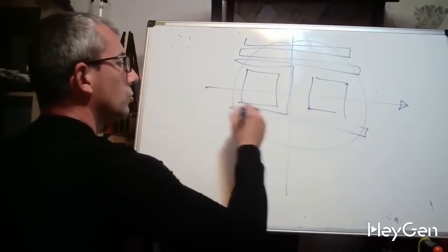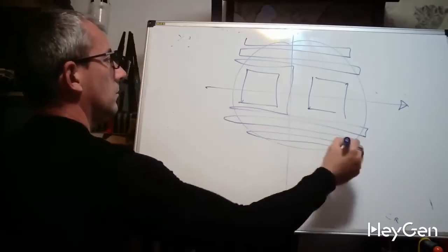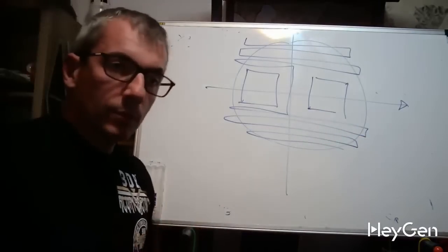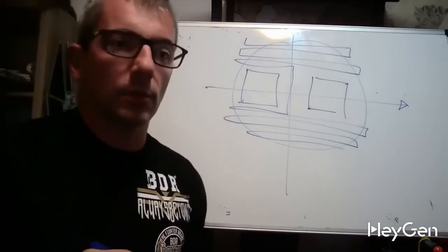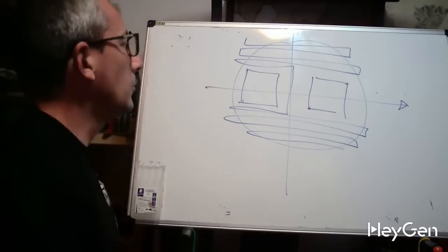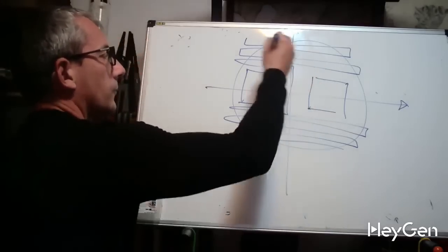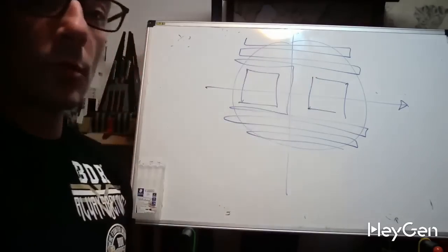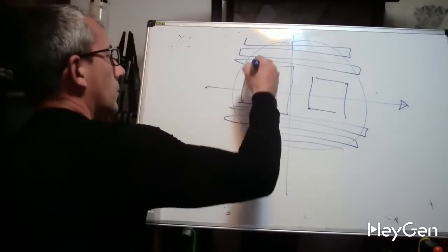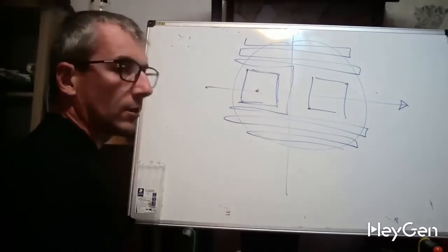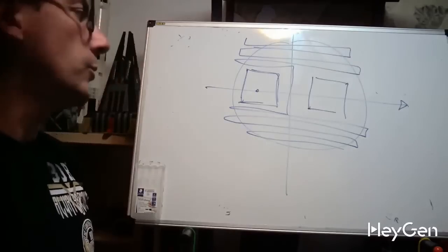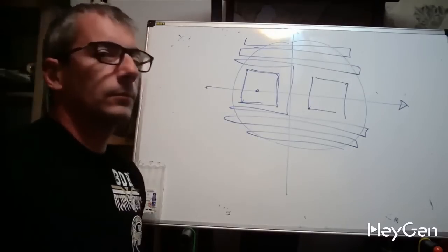That's why I recommend you check out my tutorial, fully dedicated to the manual guide, where it's very simple to empty the workpiece with a pre-established cycle in the manual guide. You can also create a subprogram and then shift the origin, but first you need to clean the workpiece. And that's the slightly more annoying part of milling.